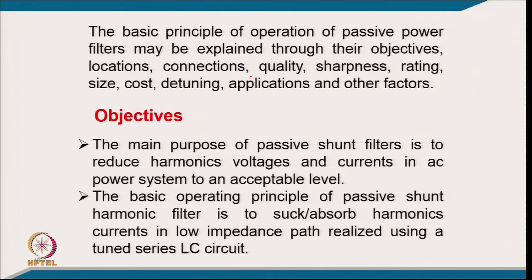With a very high impedance it should not draw any fundamental current from the supply, because they are put in shunt. But certainly at the fundamental frequency they behave as a capacitive network, and fortunately they give reactive power, leading reactive power, which most such current fed nonlinear loads need, and most of the AC network certainly has a lot of magnetic components. So, this reactive power at the fundamental frequency is really acceptable or virtually preferred, in the case of the shunt passive filter.